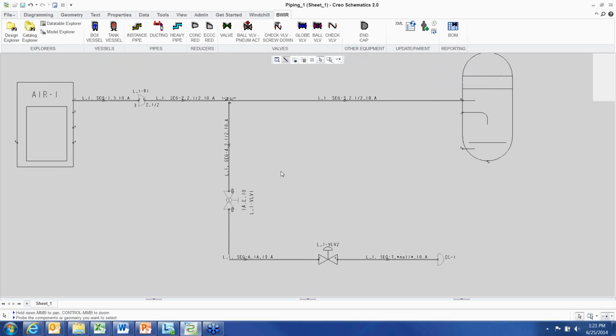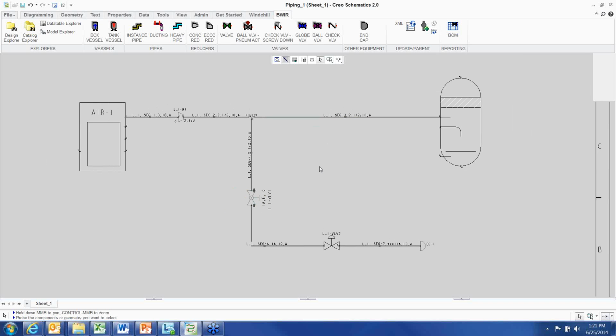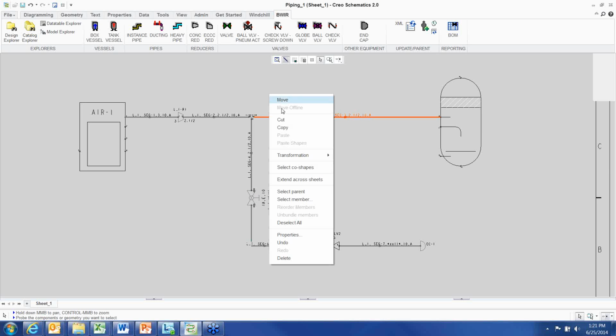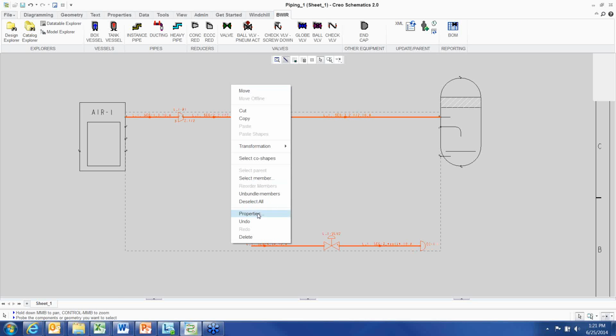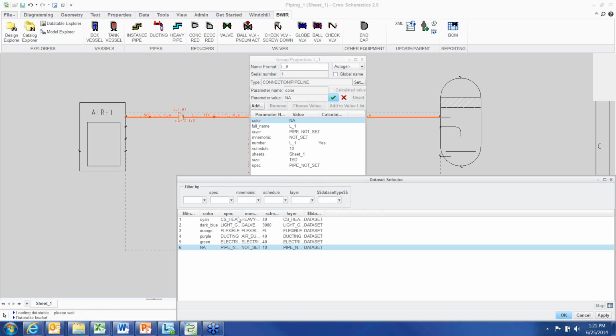All right. Now, let's say I have the pipeline. Great, what can I do with it? There are a couple of things I wanted to talk about. We can select the overall pipeline, which is the parent in this case, go to Properties, and apply an all-over top-level data set called a spec.